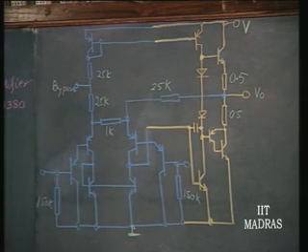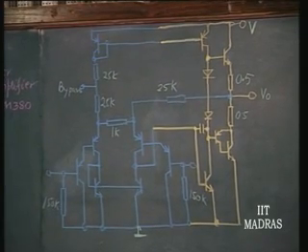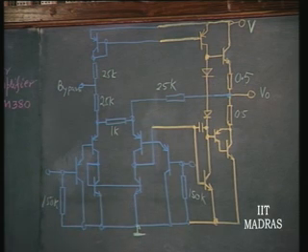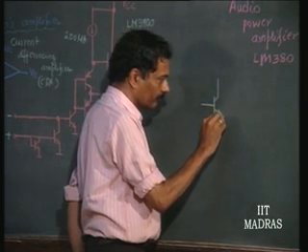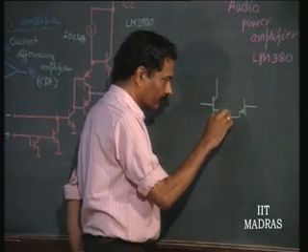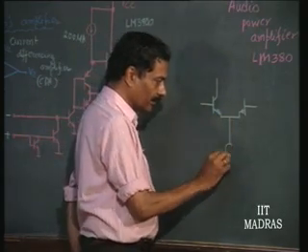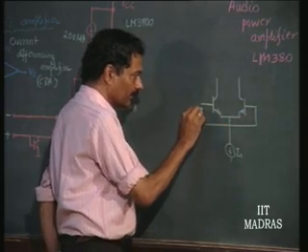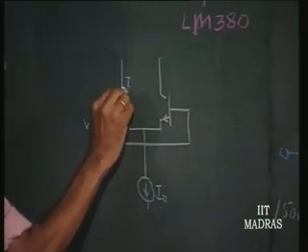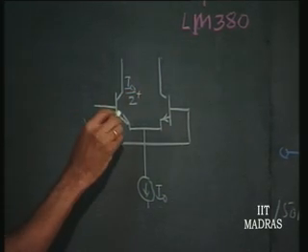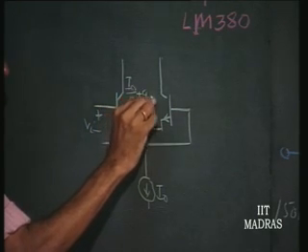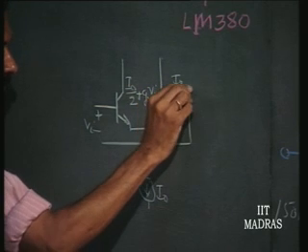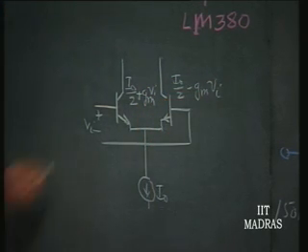So, this is similar to the input stage we have earlier discussed, except for a small difference here. Let me make that out clearly. Earlier we have been discussing differential amplifiers like this. There will be a current source here, let us say I naught. The idea is when you apply a voltage V I, this will carry I naught by 2 plus Gm times V I, and this will carry I naught by 2 minus Gm times V I. This aspect we had already discussed earlier, I am sure.